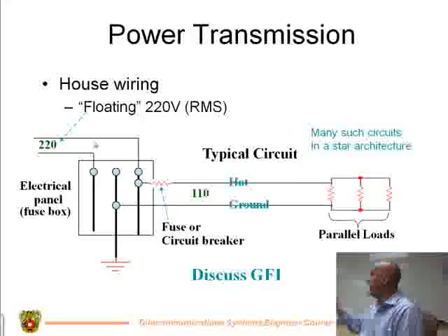Now, the idea is, what is it that trips the circuit breaker or blows the fuse? Let's use a fuse because it's easier to think about. What is it that blows the fuse? Yeah, you get a lot of current flowing through it, and it has a filament with a resistance, right? More current flows through it, more power gets generated. That power is getting dissipated as heat, which melts the filament and breaks it. So it's just the total amount of current flowing eventually burns out the fuse. And breakers work pretty much the same way. The total amount, the magnitude of the current, is what pops the breaker.